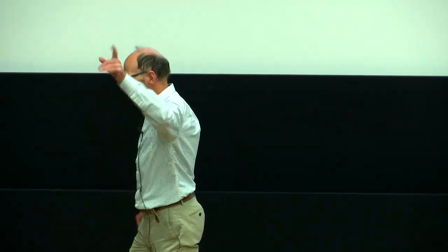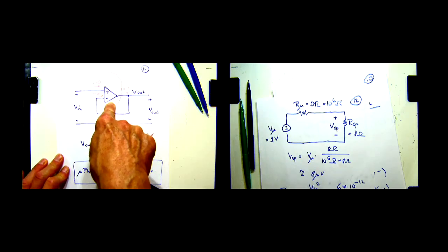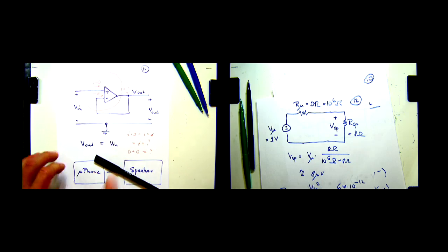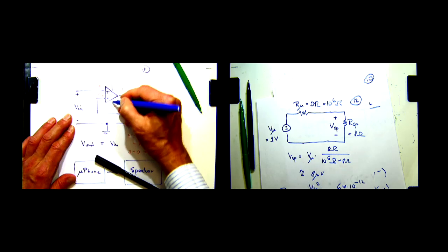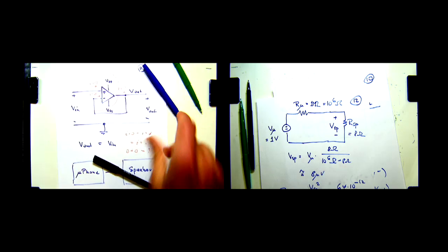Okay. So what your colleague threw out was complicated terms, VDD and VSS, also known as supply. This operational amplifier is not like a resistor. For it to do its stuff, you don't need to fill gasoline into it, but you need to hook up a supply, okay? It's not going to work without the supply. And now I'll tell you a little bit about the pitfall. When we draw circuits with operational amplifiers, when we draw the schematics, we pretty much never show these supplies. But in practice, there would be supplies. So be very careful.